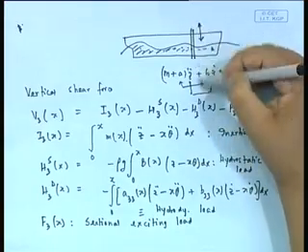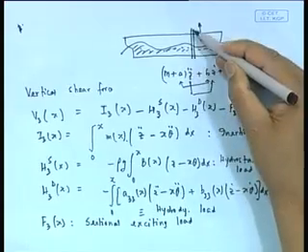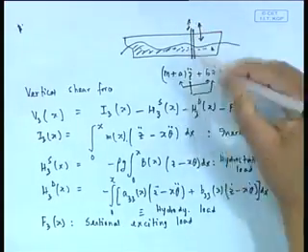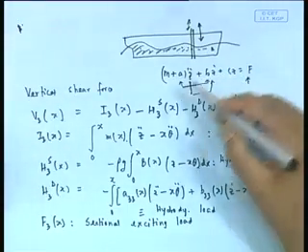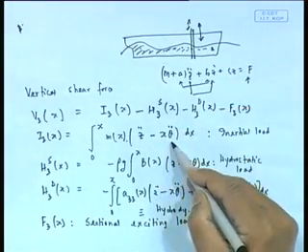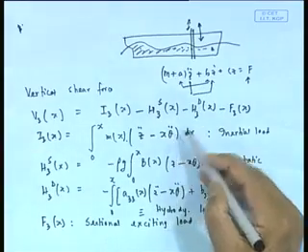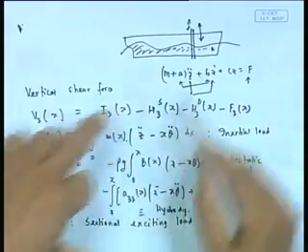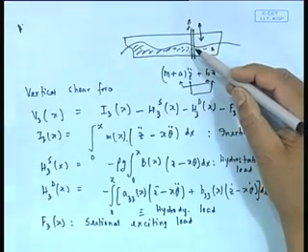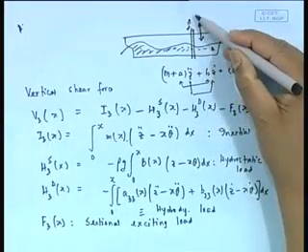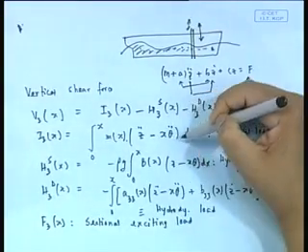Nothing else. Okay. But here, see, in seakeeping, what we are doing, I have this section. Remember, each section is undergoing a motion up and down. So this has inertial load. How much? Now this is undergoing an acceleration, a section at location x, and the vertical acceleration is going to be z dot dot minus x theta dot dot, because that is a vertical velocity. So acceleration is this. So if you integrate that mass into acceleration, you get this sectional inertial force. Now, obviously, with the vessel undergoing heave and pitch, each section is undergoing a vertical acceleration, which is arising because of the heave and pitch combination.